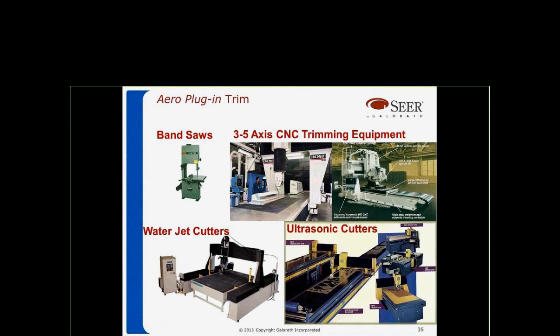Trimming of the parts is essential on composite parts especially, or any metallic parts if they have to be trimmed. But typically composite parts are made non-net, and then they will trim it finally after they've been cured.